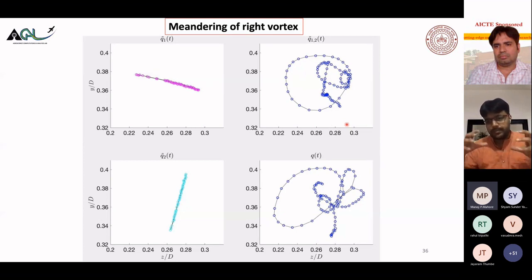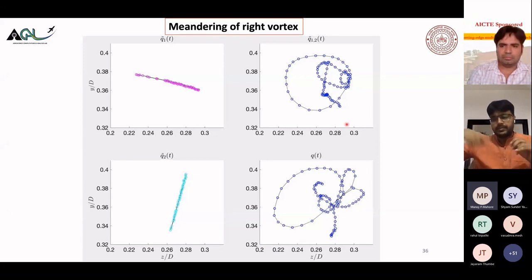So you will have the initial transient effect. If you, for example, put a probe somewhere in the flow, you will have very random fluctuations going up and down, and it will eventually settle down. Settle down in the sense that you will still have the fluctuation, but it will have a given frequency. It will not be very random. Initially we'll have very random behavior because of the initial condition, so that has to go down. Only then should you start collecting the snapshots.